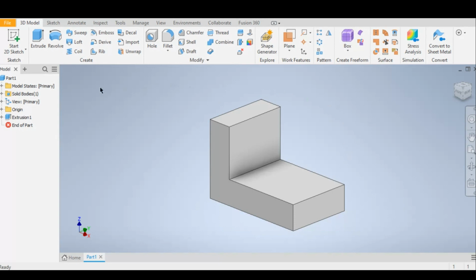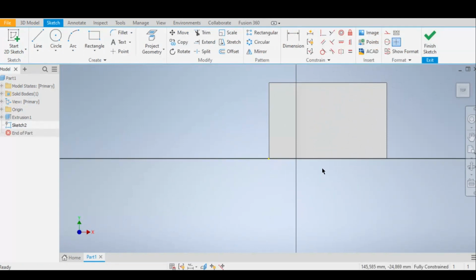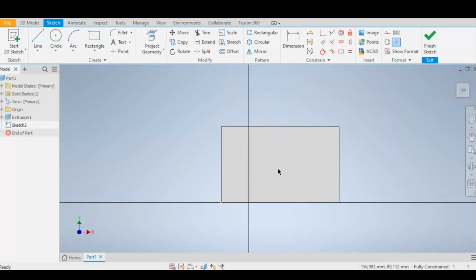We are going to head to start a 2D sketch. Once you select that option, you can then, by selecting the highlighted section, as you can see here, this will then select the area where you will be drawing whatever it may be onto this 3D model. So let's draw onto this plane here, and as you can see, once you select that section, Inventor will automatically rotate your parts into the correct orientation for you. So let's do a rectangle today here.